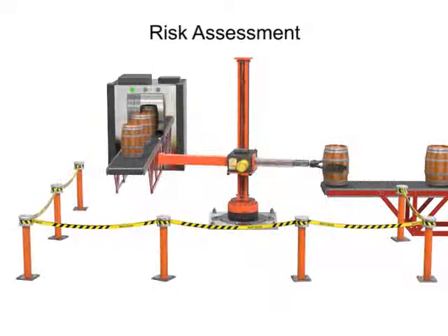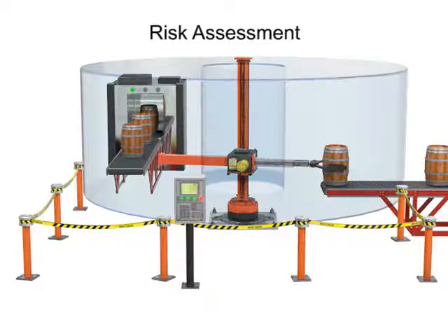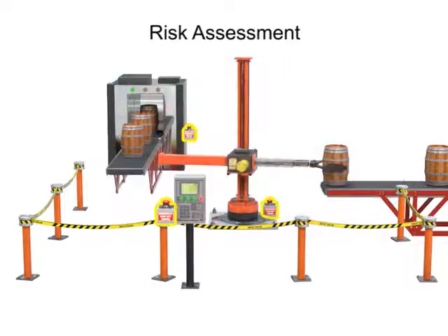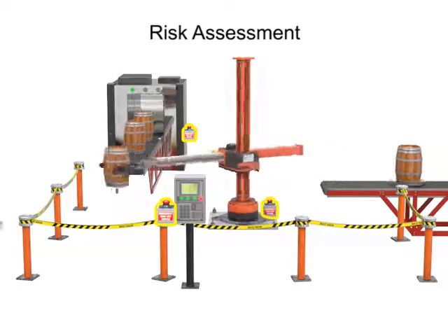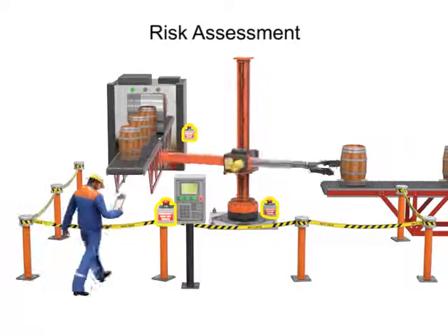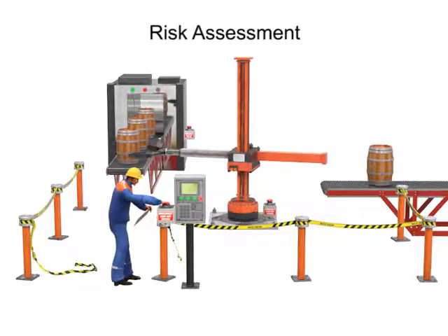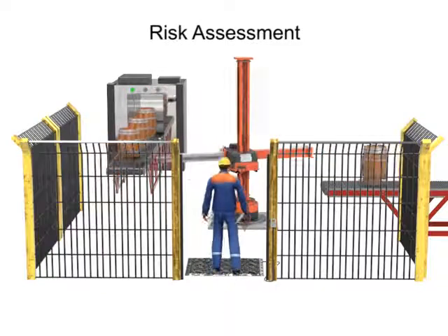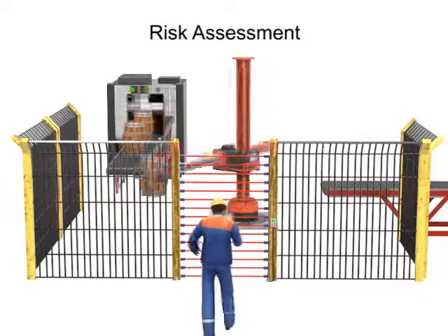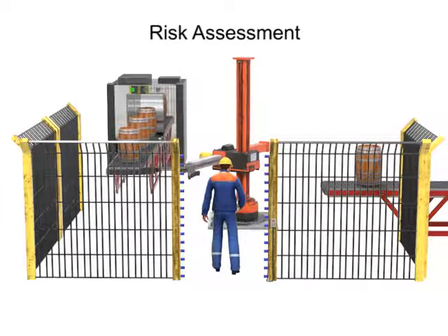The design and location of control panels are also fundamental to a safe robotic design. The control panel should always be located outside of the work envelope but within sight of the robot. Emergency stops should be located in all zones where needed and should be a large part of emergency personnel training. If the proper safety measures are used, robots can be a highly efficient, safe way to accomplish work.